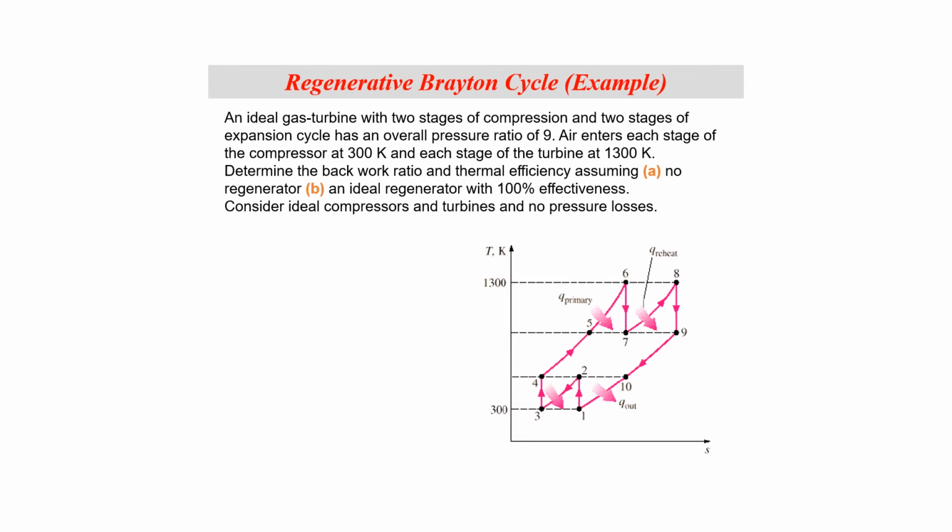In the reheat and intercooling cycles, one important thing is that now we do not care at which pressure we are reheating the system from. For example, H6 will be equal to H8, and similarly H5 will be equal to H7, which will be equal to H9. Similarly, H1 will be equal to H3, and H2 will be equal to H4.